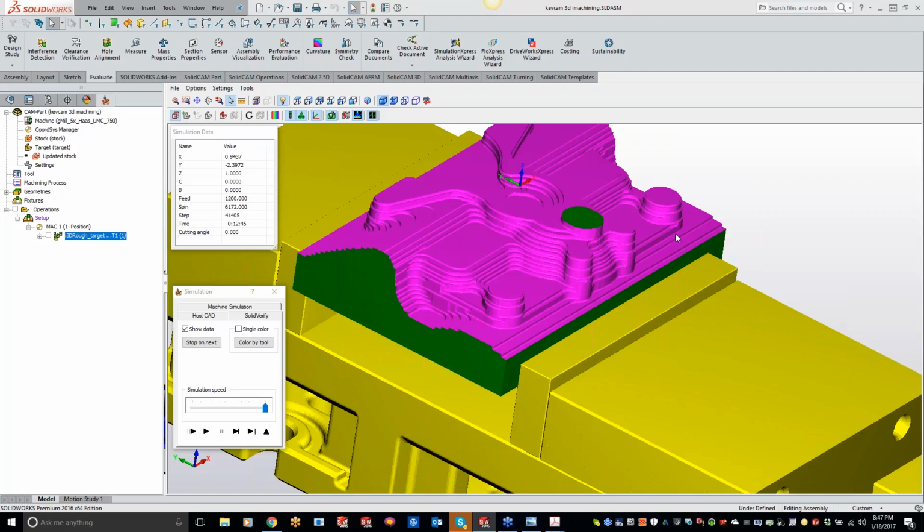So by doing it this way, we're saving machining time, but when we come back to do a finish pass on here, that load and unload of that ball end mill is going to be the same throughout the entire cut. So on a more vertical wall, let's say the old way, these scallops would be much smaller, so you're going to get a different finish versus over here where that scallop is going to be that specific size.